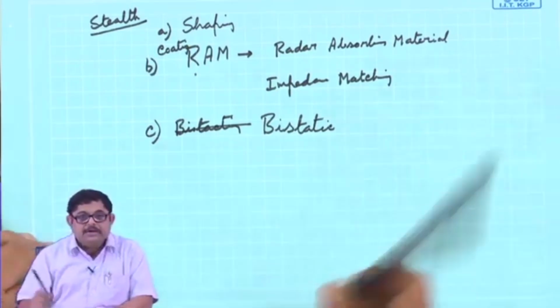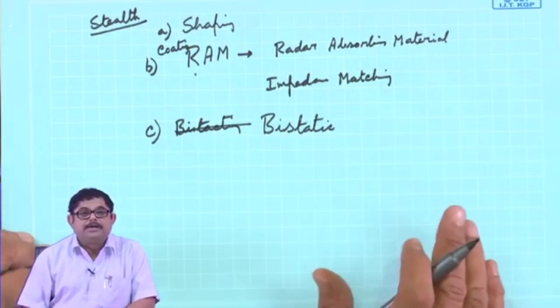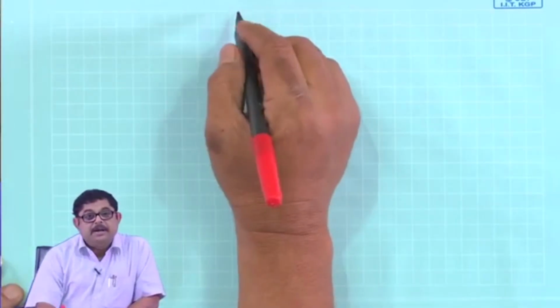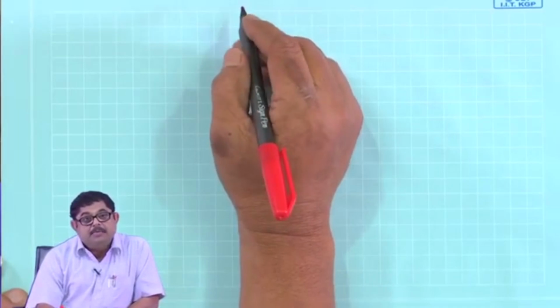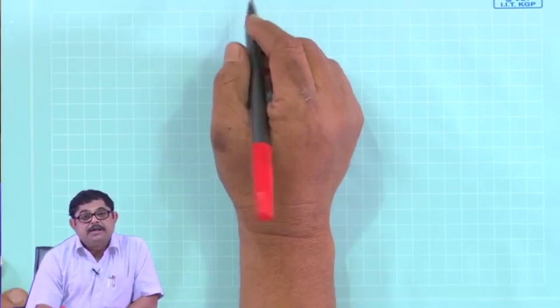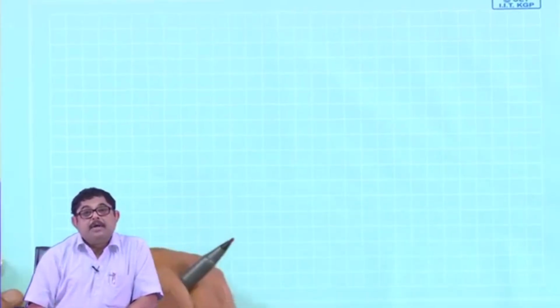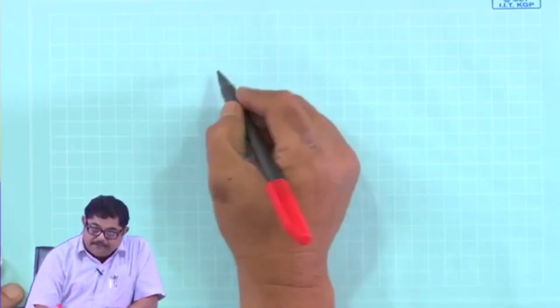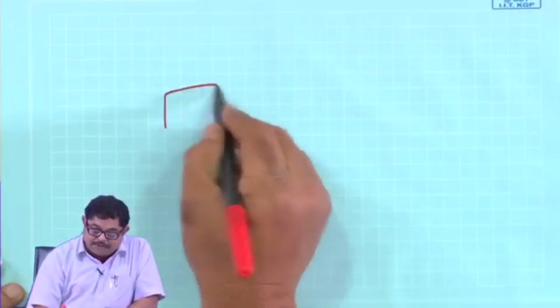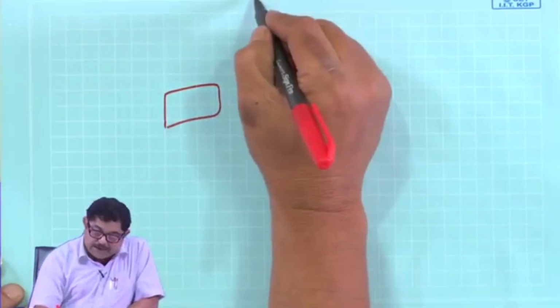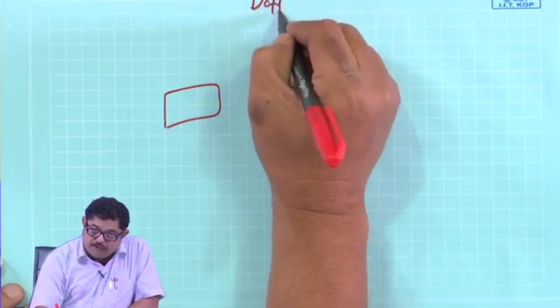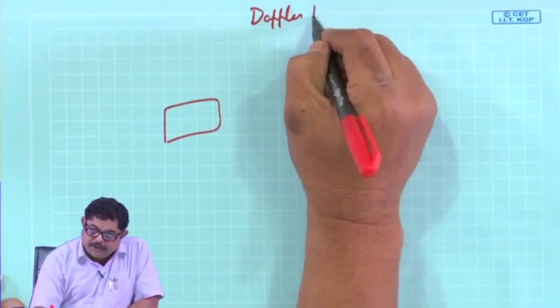So, this is somewhat a brief discussion on RCS. Now, we will see another parameter and we will close. Actually, after range measurement, one more important measurement that the radar does is the velocity of the target. Now, I can say that suppose a radar, so the parameter that I am going to discuss is the Doppler effect.